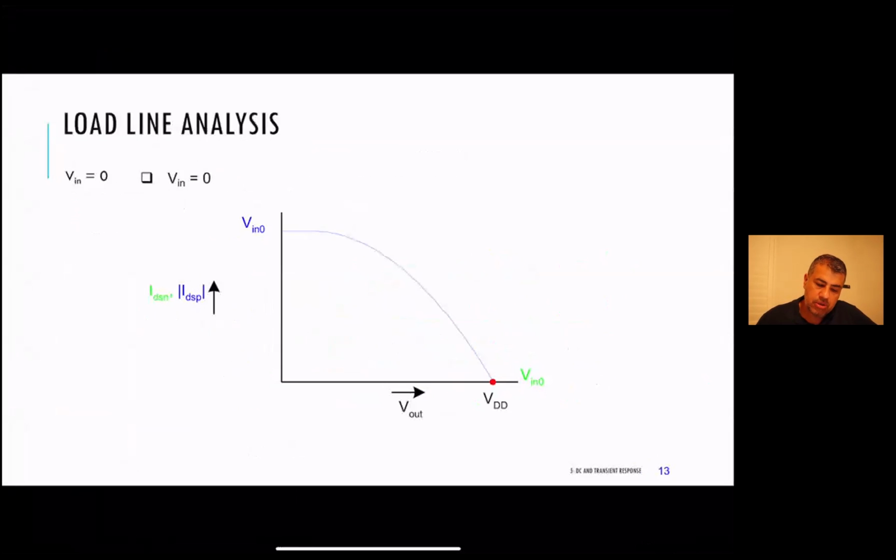Okay. So again, in the case where Vn is equal to 0, that's the blue. When Vn is 0, the PMOS has a lot of current, right? So it has that VDS versus IDS curve, and the NMOS has 0 current. So where they meet is at VDD. So when Vn equals 0, the output is at VDD, which, as a starting point, is good news.